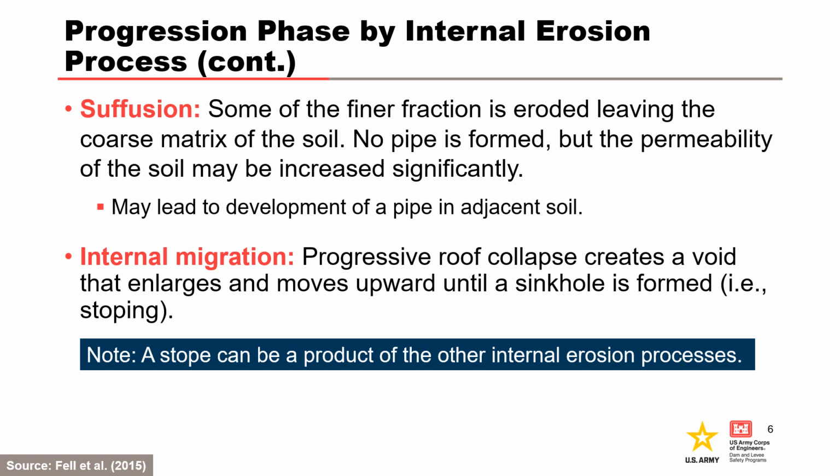For suffusion, some of the finer fraction is eroded, leaving the coarse matrix of the soil. No pipe is formed, but the permeability of the soil may be increased significantly.